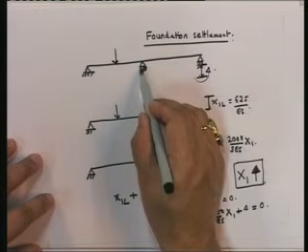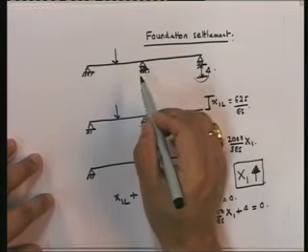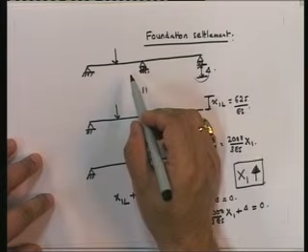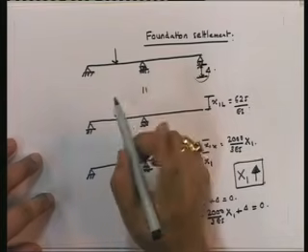Okay? In other words, lack of fit does not normally have any effect on beams, because lack of fit has an effect on axial forces. And remember that in beams, okay, axial forces are not of major consideration normally. Okay? So, that is why lack of fit is not a major issue as far as beams are concerned. So, that is why I am not considering that right now. However, thermal stresses can have a large effect.